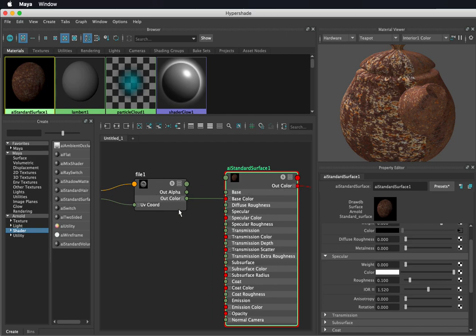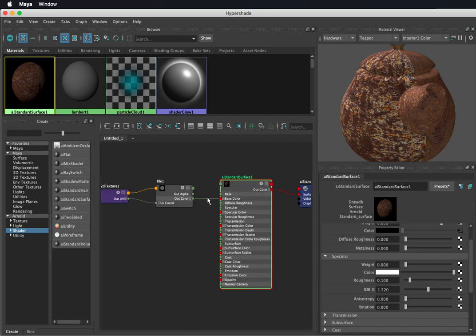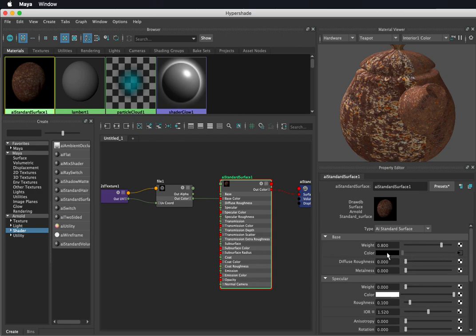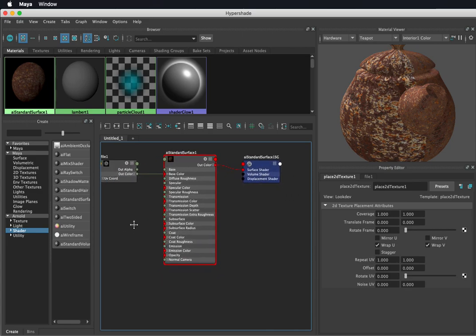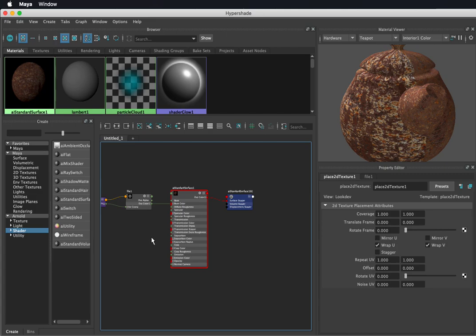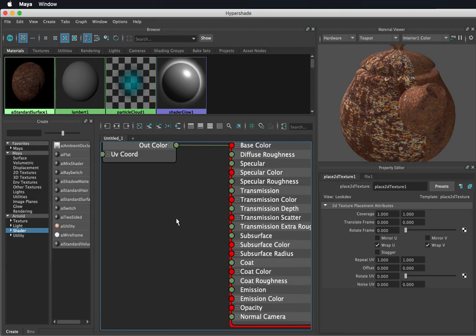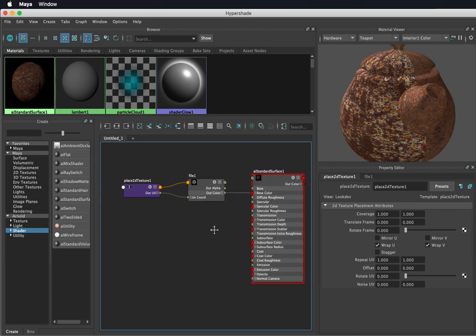Okay, so that's one way we can attach a file to our scene. If we decided we didn't want to have that file attached anymore, we could right click here and try to disconnect that. But an easy way to do it in the node editor is just to select and drag over here. Mind you, I'm just moving around by using the normal Maya tools, so Option and middle click to pan, and then using my mouse wheel to zoom in and out.